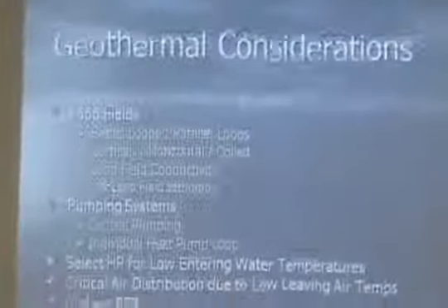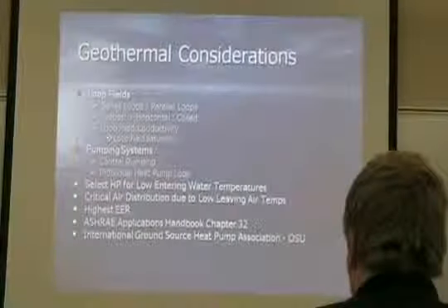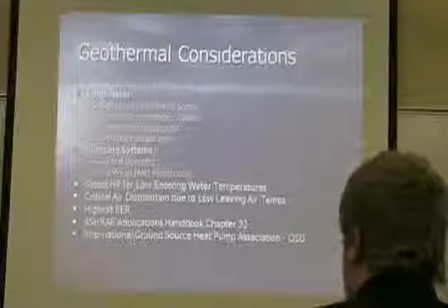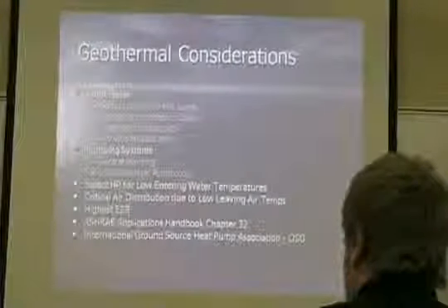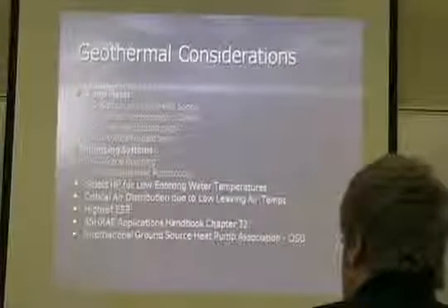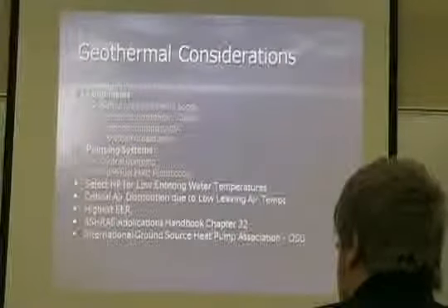I wonder what the drawbacks to those are, the algae, things like that. Well, the algae not so much, but the mussels. I knew that happened down on the river. Yeah, there are some applications here in Little Rock that had problems with mussels covering up all the pipe. You don't get any heat exchange anymore.